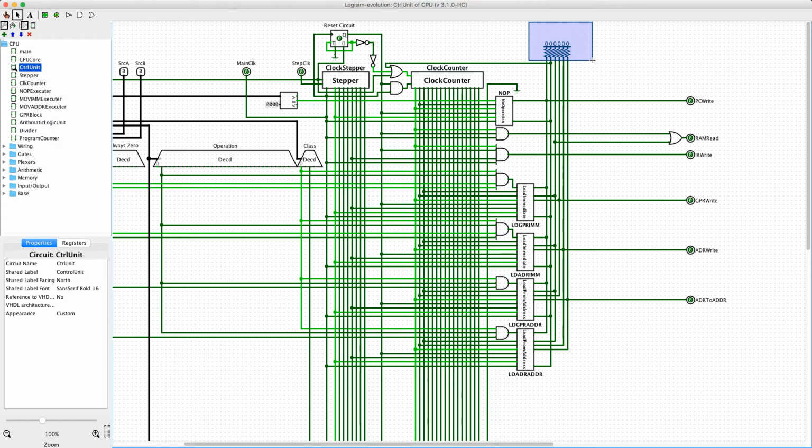And these pull-down resistors just make sure that there's no loose signals activating any registers, although I don't have to worry about that on Logisim. I would have to worry about it in real life, because if more than half of the controlled buffers are trying to output a high signal at the same time that they are all outputting a high impedance signal, then the enables on the registers will register as a logic high, and that would erroneously write data to the register when the clock pulse went through, and that would be bad.